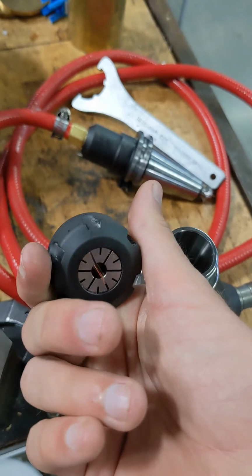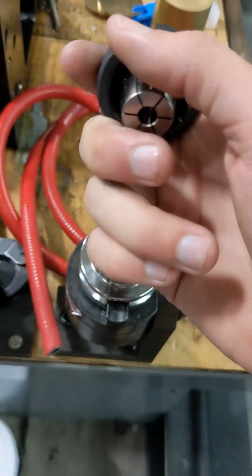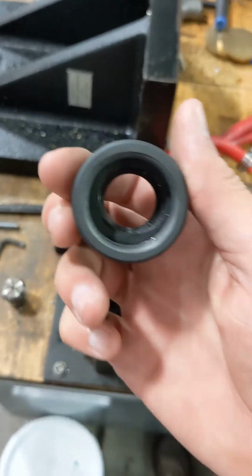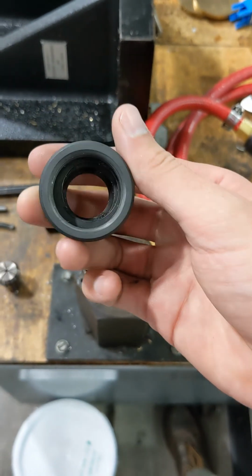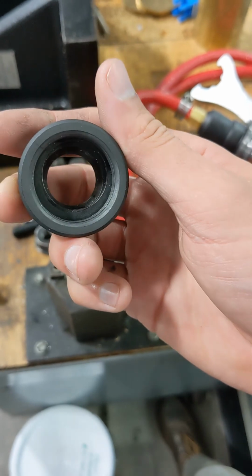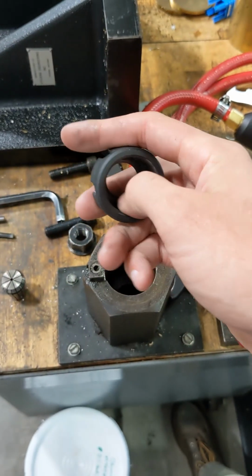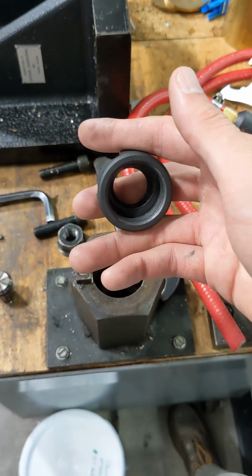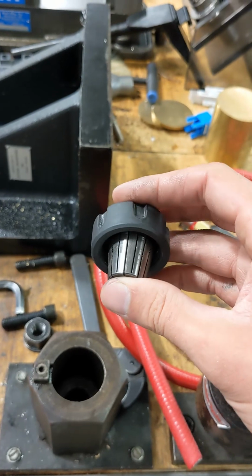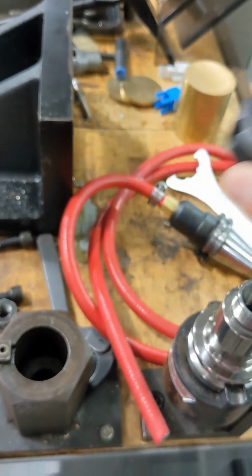This is the half nut with the collet in it right now. We are going to take the collet out. You'll see, I'll take it out and then you can see the inside of it. On the inside of the half nut you can see there's a little lip that's offset to one side. That is the lip that holds the collet in place. So what you'll do is you will insert your collet onto that lip and then push it upward. So the collet will then be seated on that lip. So I've just pressed one side of the collet on it, and then I will press the other side up until it snaps, and now it's held in place and it should be flush.